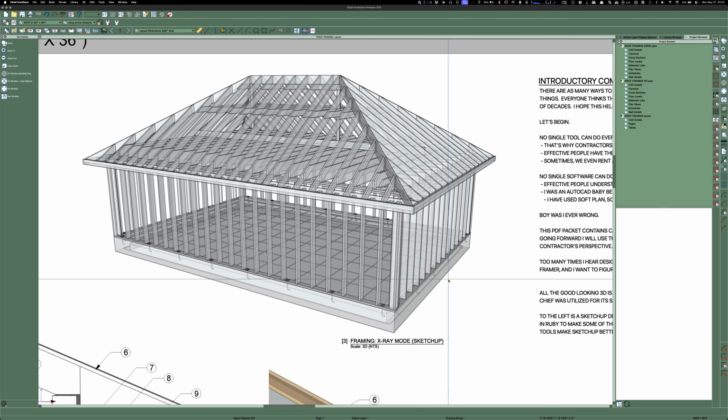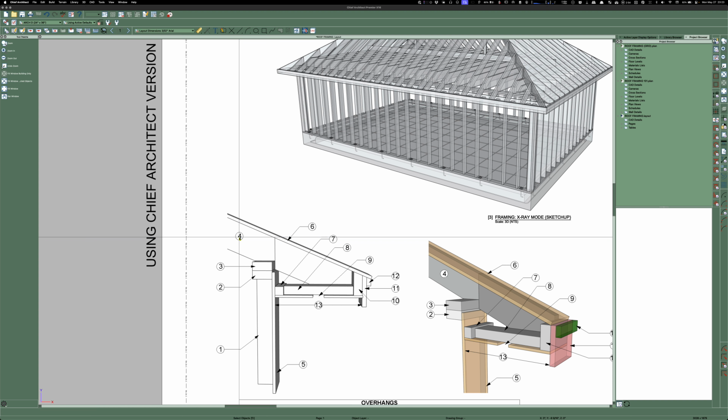But this all got started because the way Chief measures its rafters doesn't help me set up a cut sheet. So they have made some changes. Now when you double click a rafter, it goes from the long point at the top down to the short point inside the subfascia. So that's pretty cool. That's different than what it was just last year.